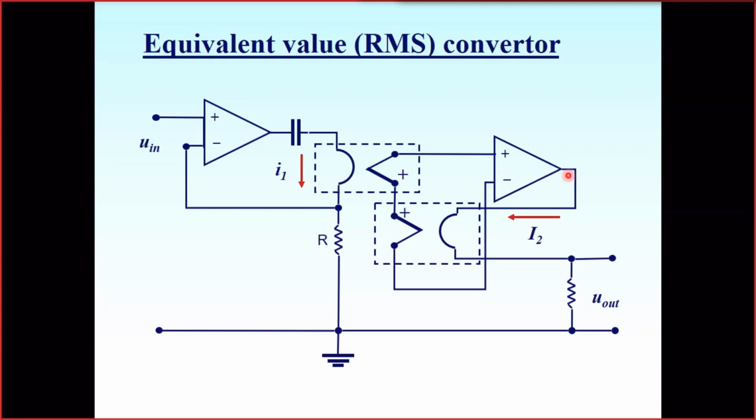This voltage causes a current to appear through the output of this amplifier. And this current will grow until it is so high that the heating of the second thermocouple becomes equal to the heating of the first thermocouple. Then the electromotive forces are compensated, because they are switched one opposite to another, and the voltage here will drop. So in any case, we have a balance. We raise the current to counterbalance this rise in the electromotive force because of the heating of this heater.